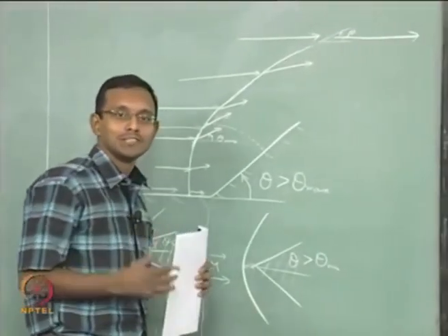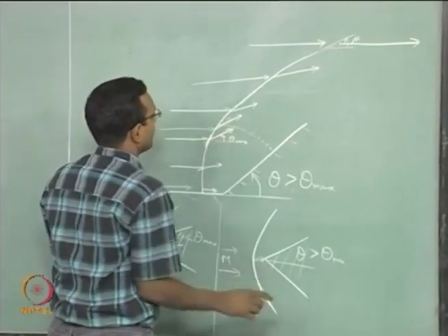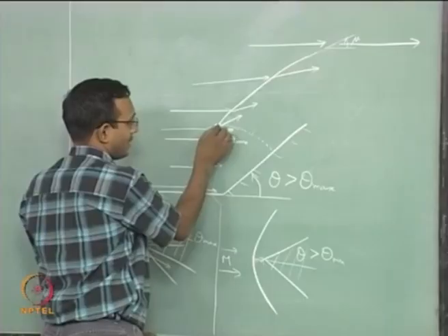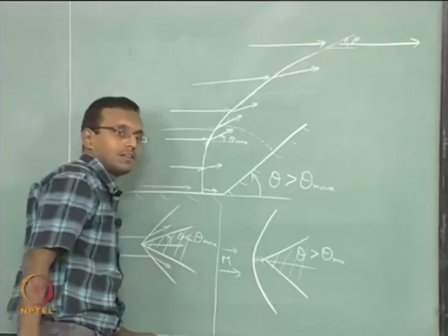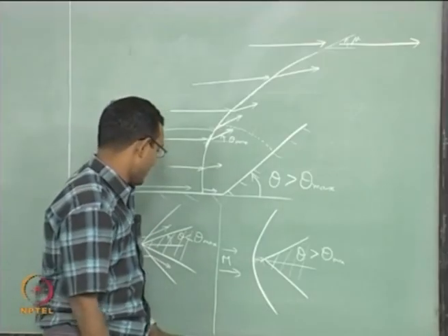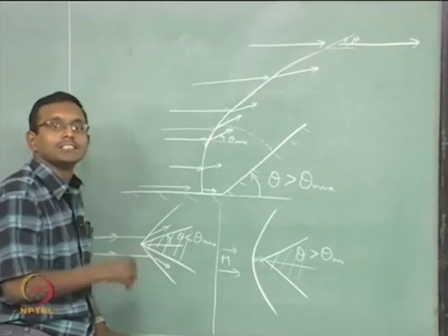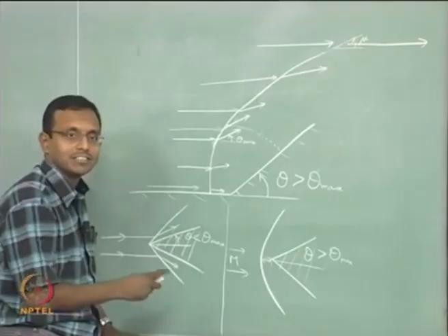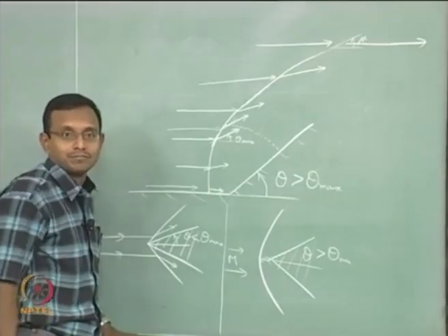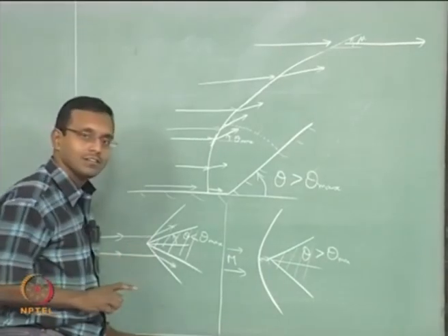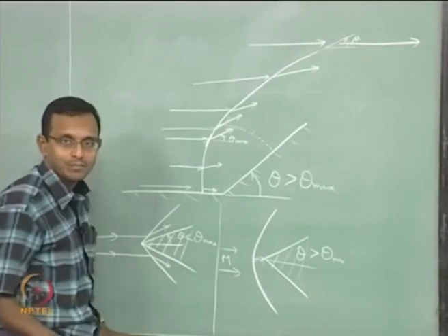And of course m equal to 0 also, when there is no flow, no shock, we will not worry about it. So I have this whole region inside this curve, all the way inside this whole range, as all subsonic flow. All this time when I had this nice attached shock condition, the flow could adjust to the change in streamline direction by just having one attached shock. That was enough. Just a change in angle of the flow direction, and just one oblique shock was enough.